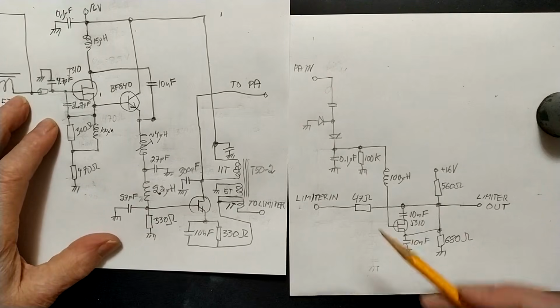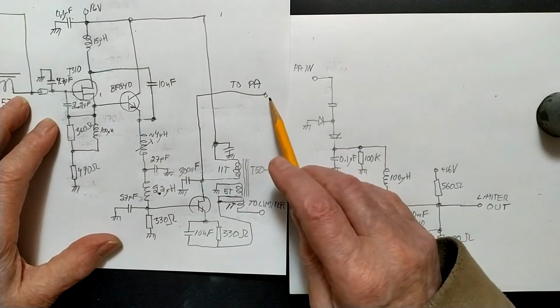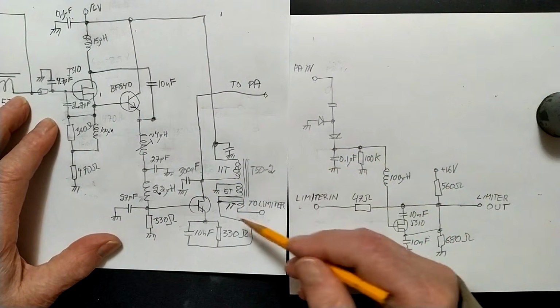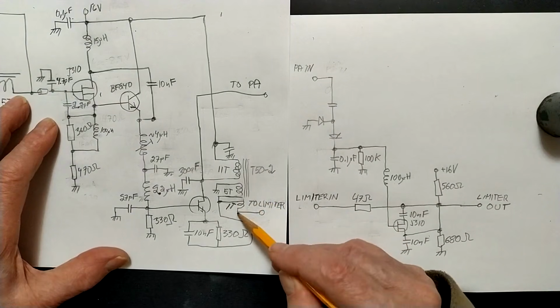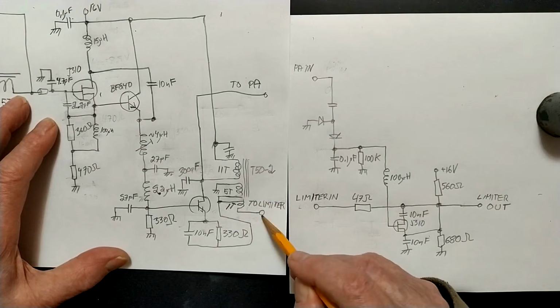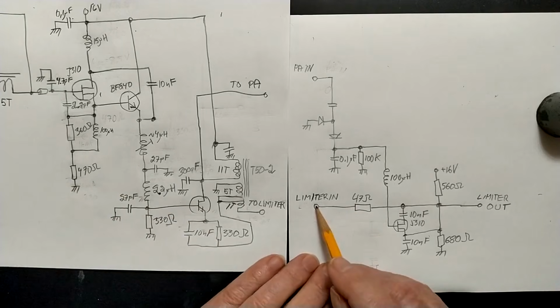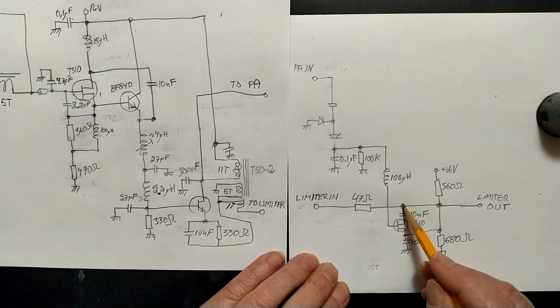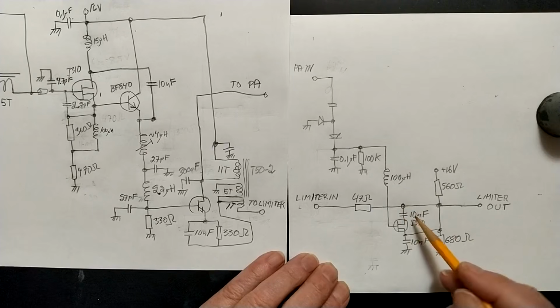I will use the signal from the collector of the transistor to feed the power amplifier, and I added 1 extra turn on the transformer to get the suitable level to feed the limiter. And then the limiter is a resistor and a FET that I can control to attenuate a little.